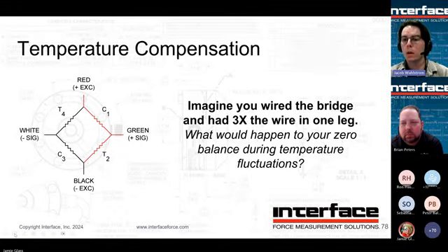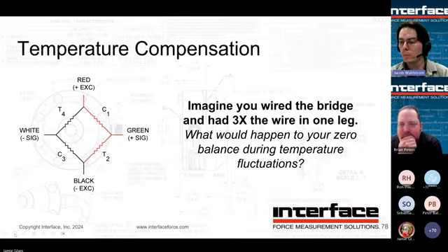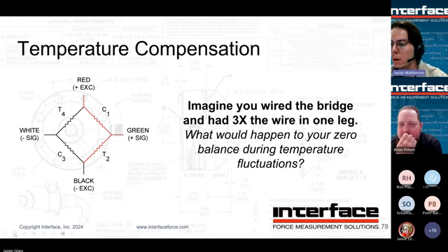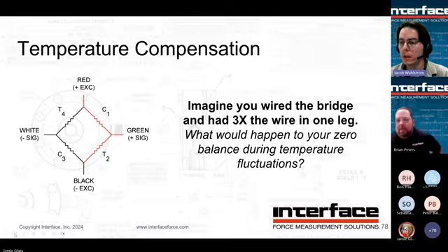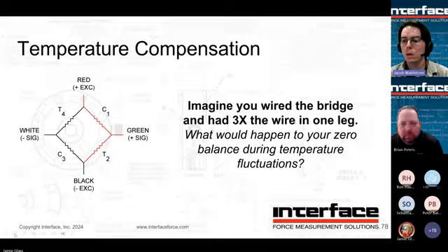So that's very important when considering the assembly of a load cell. You really want to position your gauges and take into account the wire length that you're using to connect your gauges and your bridge. And I think I saw a question here about if I'm operating at constant temperature that is outside the specified compensation range, will the output be as accurate as long as I first zero the output? And that's accurate, yes. So if you go to a temperature and you're able to zero it out, or you know that that's the new zero, from there you'll have accurate readings.